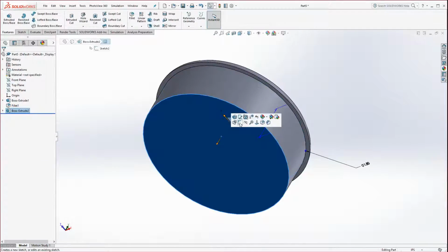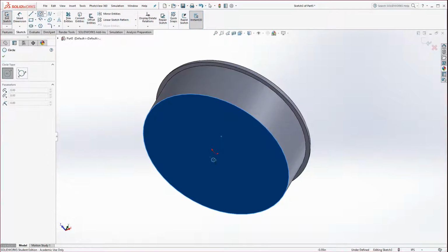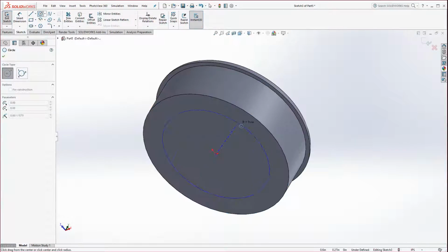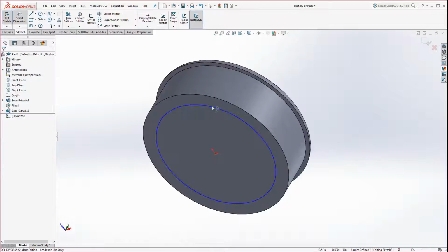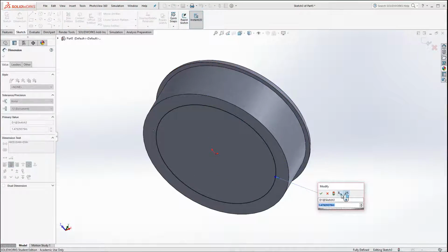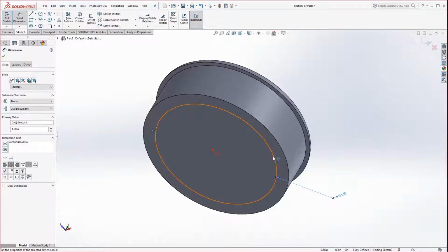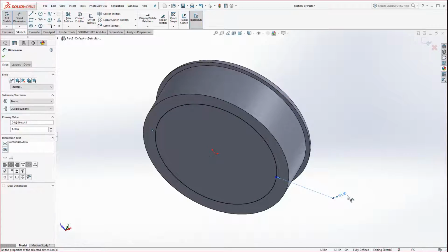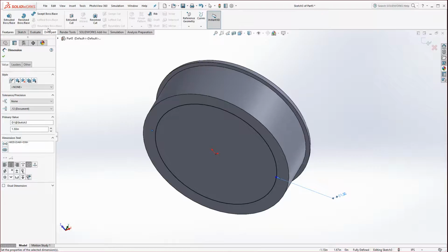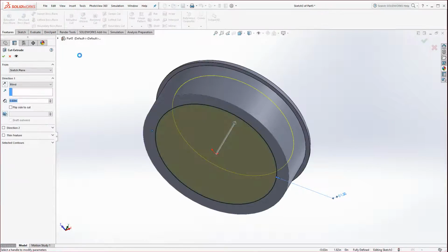Now you could go ahead and put the hole in it. Do not shell. Again, don't try and take shortcuts unless you really know what you're doing. Just from experience of grading these tests, you want to draw the diameter in here on the center, 1.5 inches, and that gets extruded only 0.4.